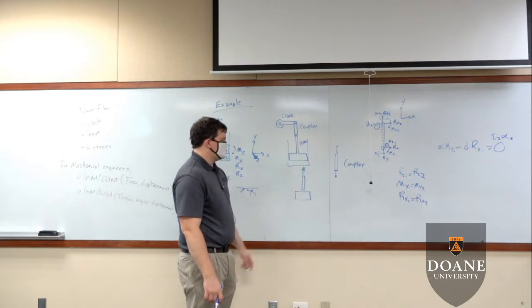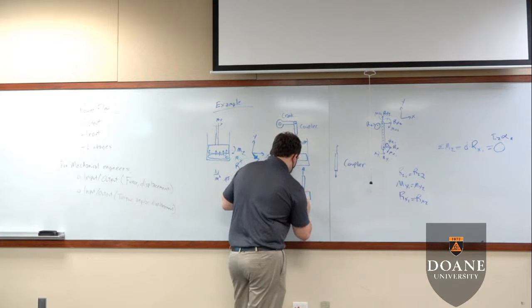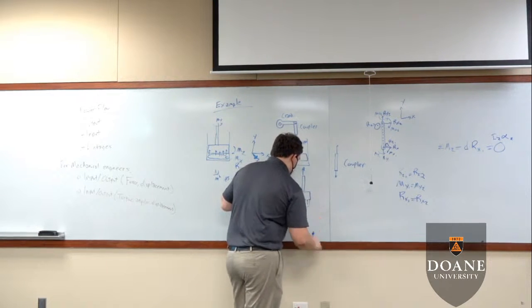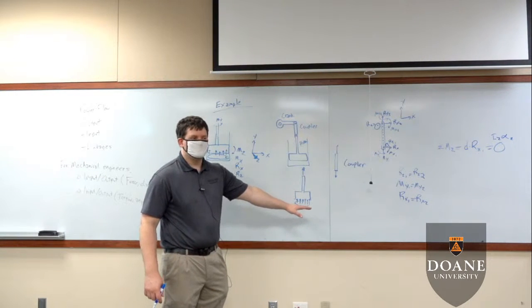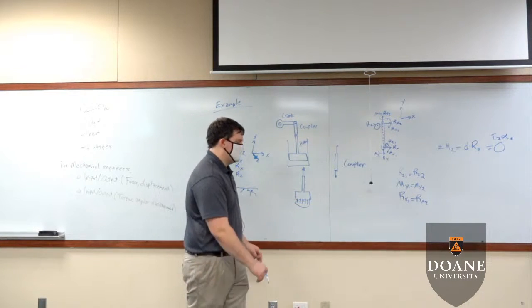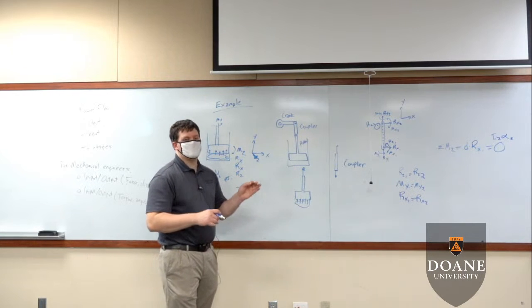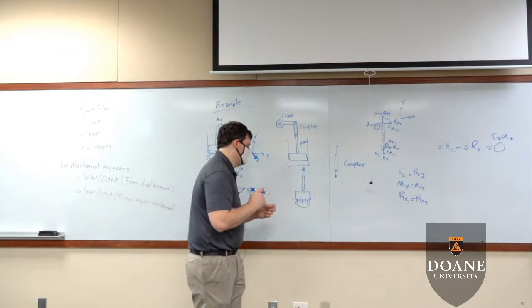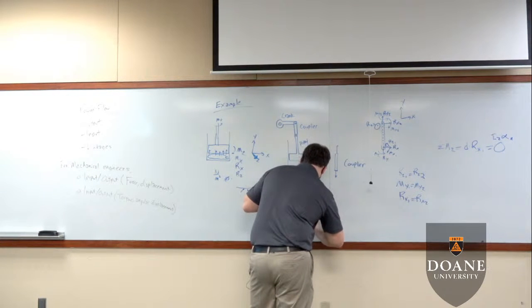Now, this piston head has a pressure down here. We're going to assume it also goes upward. We can sum all of that pressure by integrating it over the area and come up with a net force in the y direction that's being exerted on the piston head. And we're going to go ahead and call that Fy.